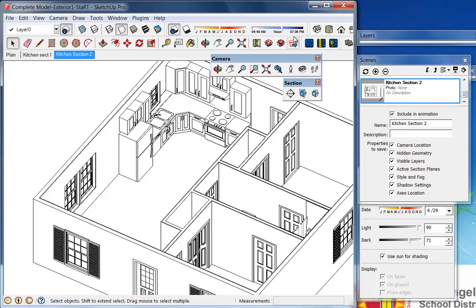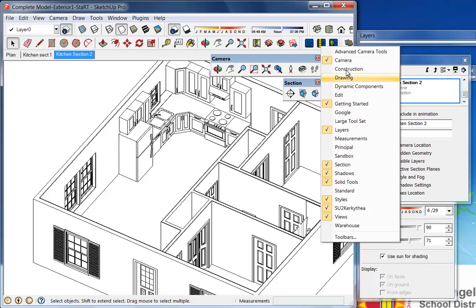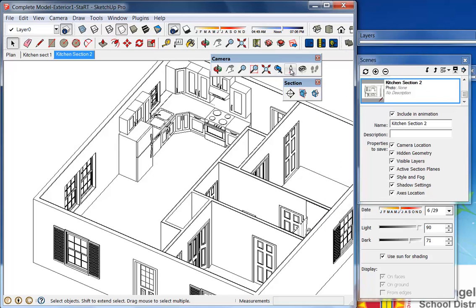So if you don't have your camera toolbar, make sure you right-click over the toolbars, and you could call it up. And what I'm going to work with first here is the position camera tool. When I activate that, I'm going to click onto the floor, right? Actually, remember, there's no floor there, so what I'm clicking on right now is 0, right? So we'll have to adjust our eye level. So here, I'll click, hold, drag, and then drop it onto what's going to be my focus.